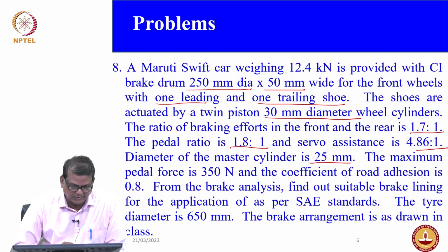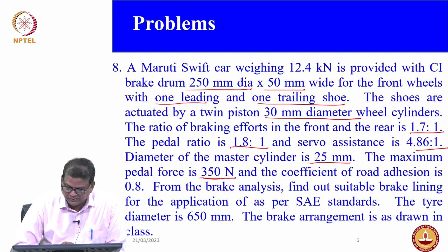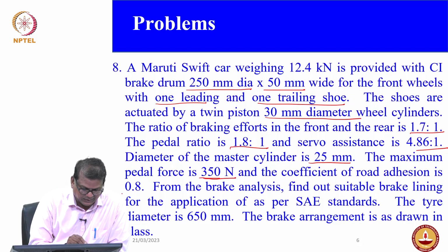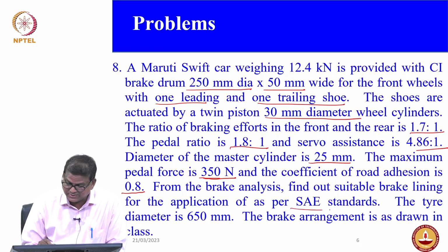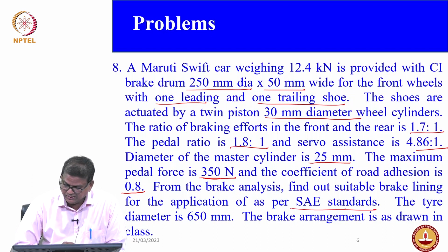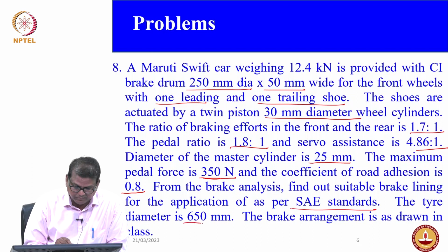The maximum pedal force is 350 Newton and the coefficient of road adhesion is 0.8. From the brake analysis, find out the suitable brake lining for the application as per SAE standards. Of course, the tire diameter is given as 650 millimeter.